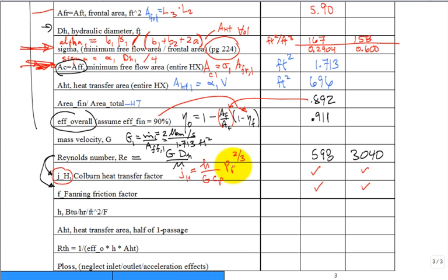It looks like it. So once we have the Colburn heat transfer factor, you get H as J times G times C sub P divided by Prandtl to the 2/3. It's just like you said, get the Nusselt number, then unravel it. Well, this time it's embedded in what they call the Colburn heat transfer factor.